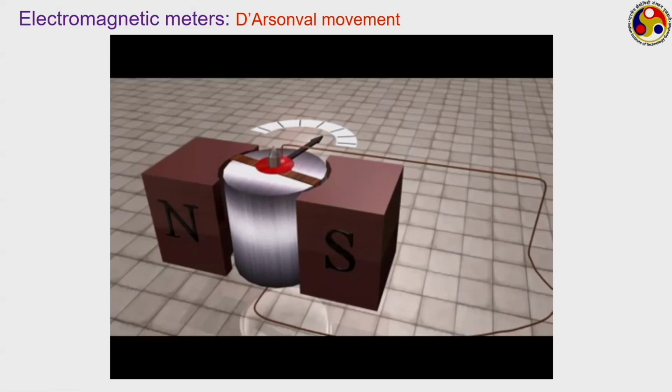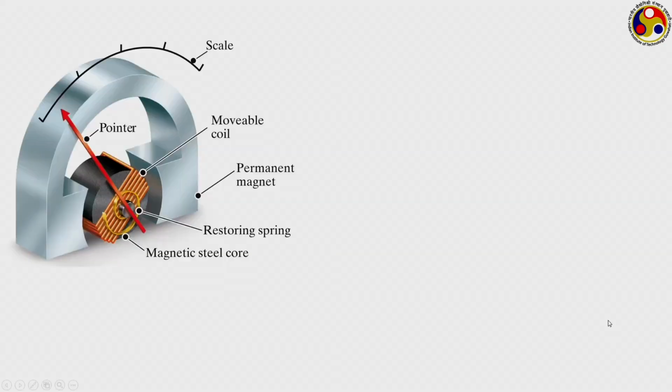So you can see this is principally an electric meter, or I should say a current meter, which gives you a measure of the current, because with proper design the torque produced by the interaction of these 2 magnetic fields can be made proportional to the current. And if we want to use this for measurement of voltage, then we have to make certain additional arrangements, as we shall be seeing shortly. But this is just a picture of the same. Now if we say that I is the DC current flowing through this, DC refers to direct current, but just as we talk about current and voltage in both DC and AC sense, we are going to use the term DC current, though it does not sound good.